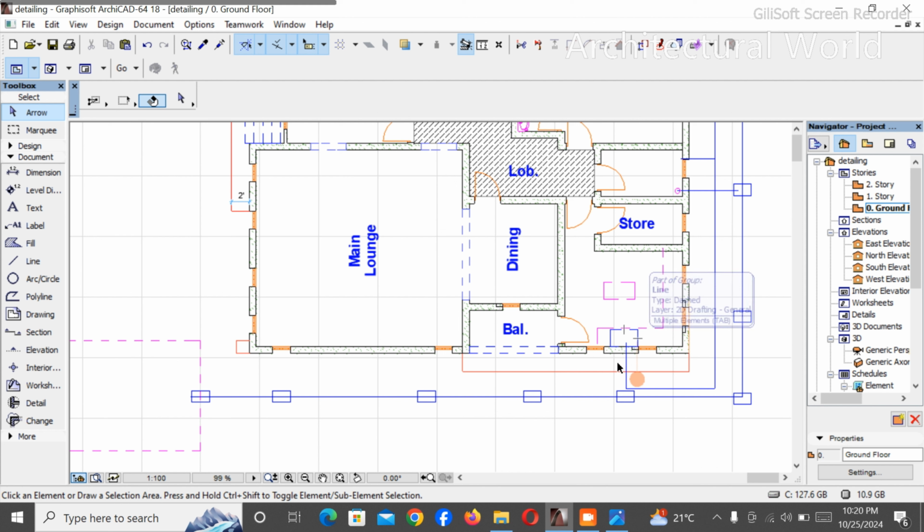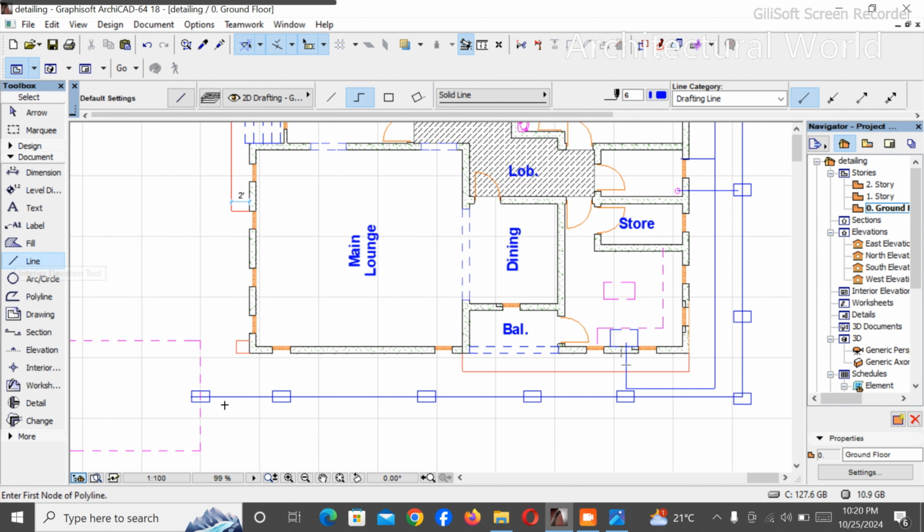Then you step the 3 inches up to 6 inches. You lay a straight 6-inch pipe, heavy duty, direct to this pit without using a chamber. I can't say there is perfection, but you have a 90% chance that there won't be blockage. So you won't be needing all these chambers. You use 3 inches to connect it, then you step it up to 6 inches, then you lay it straight one way.